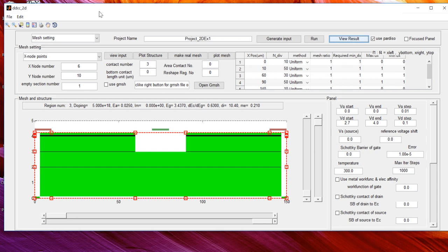Do you know what I mean? We assume a layer is the same as the P-GaN, and usually we say ITO is conducted by N-GaN, but here we say it's conducted by P-GaN. But this P-GaN is not the real P-GaN. We use impurity to force a certain amount of hole density, and we set a certain fixed mobility, so we let the sheet resistance be equal to ITO. So we're going to add a P-GaN layer, but we are going to change the doping level?